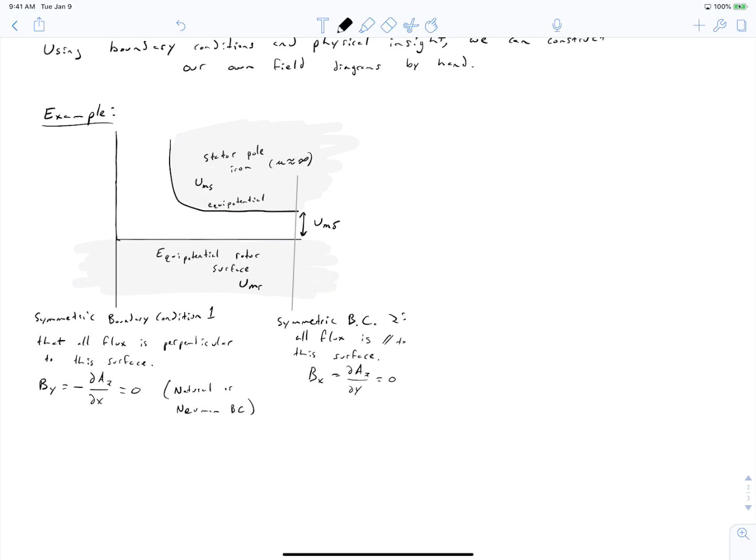So let's say in our case, we'll draw this as 4 different potential levels. And starting from the right side, just given the geometry of our structure, we know that the potential differences must distribute themselves equally. There's no reason, just given the uneventful nature of the right side of the diagram, the spatial distribution of the potentials must be equivalent. And then as we follow this geometry around, our top potential is going to tend to track the rotor surface.